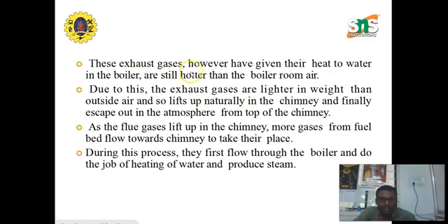These exhaust gases, however, although they have given their heat to water in the boiler, are still hotter than the boiler room air. Due to this, the exhaust gases are lighter in weight than outside air and so lift up naturally in the chimney and finally escape to the atmosphere from the top of the chimney. As the flue gases lift up in the chimney, more gases from the fuel bed flow towards the chimney to take their place. During this process, they first flow through the boiler and do the job of heating water and producing steam.